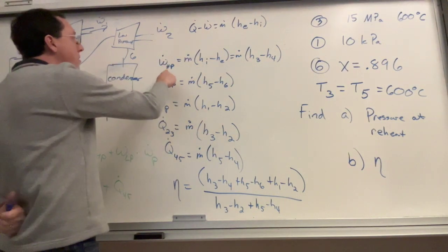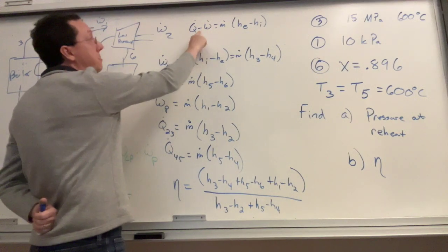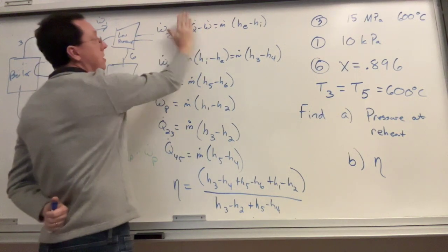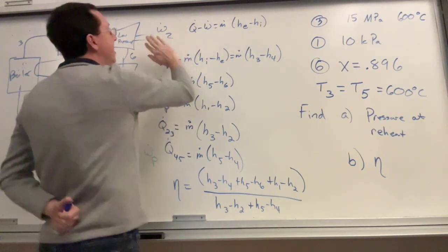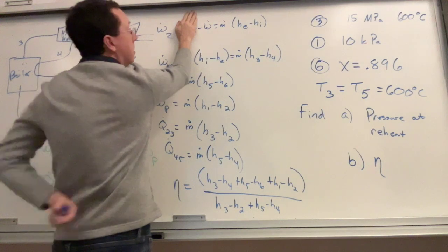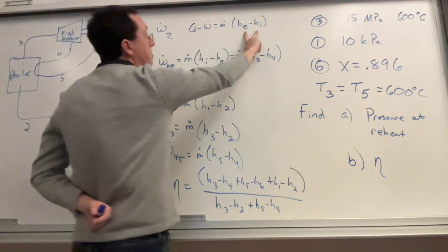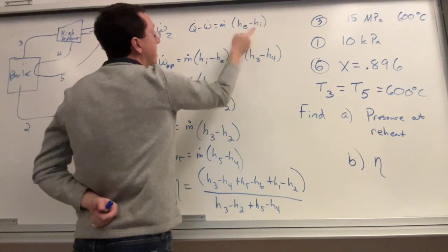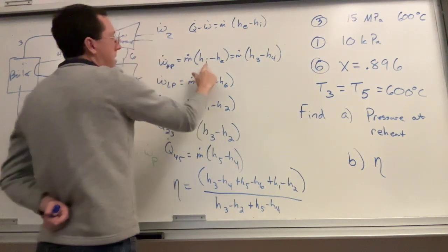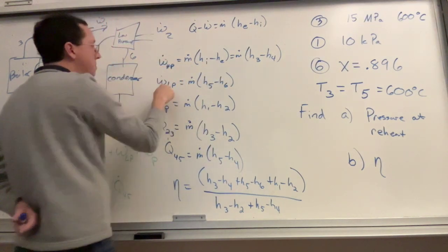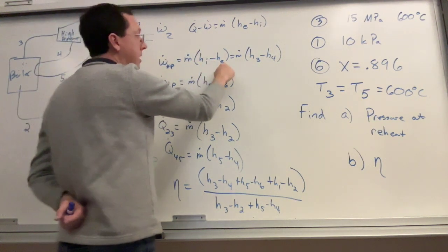To find the power of the high pressure turbine, the power, that's W dot, has a minus sign here. There's no heat for that. The HP is high pressure. And to get W dot, you have to bring the minus sign over, which means it's going to be ingoing minus exit. For all of these power producing devices, it's the ingoing enthalpy minus the outgoing enthalpy.